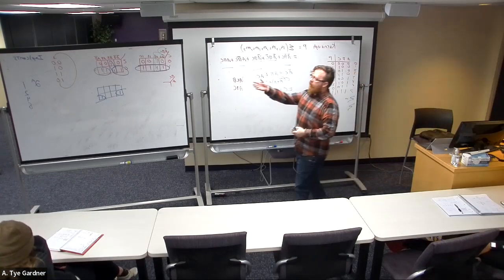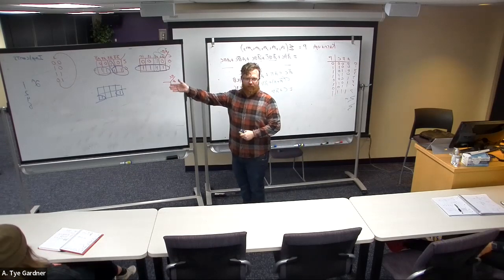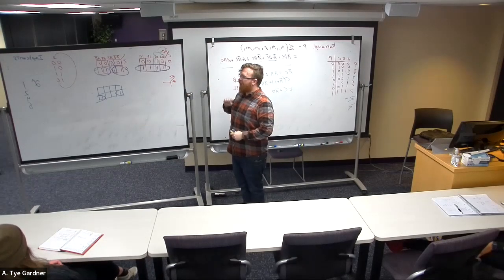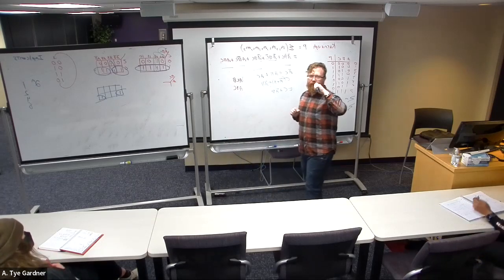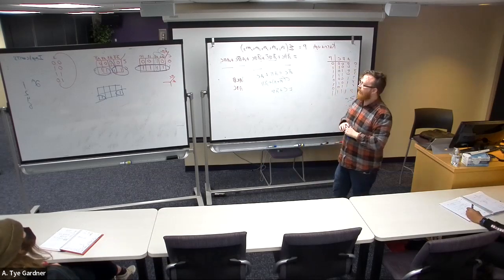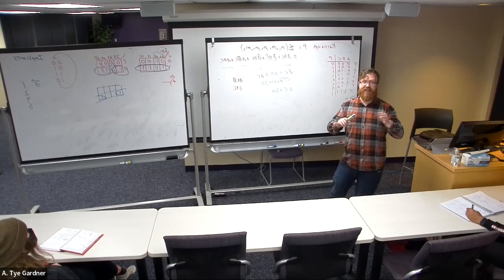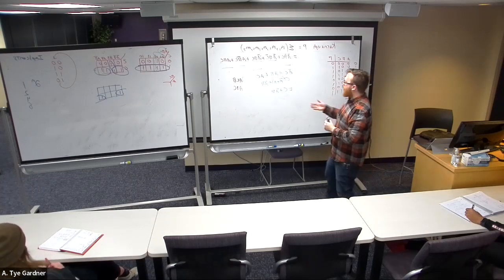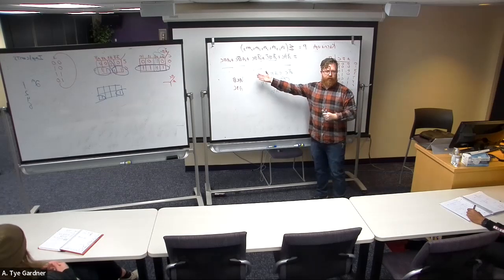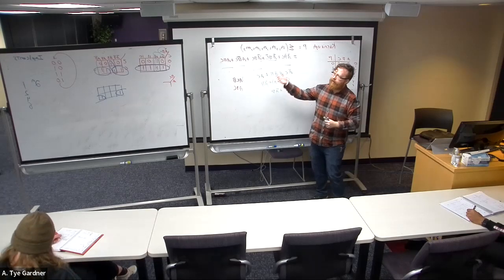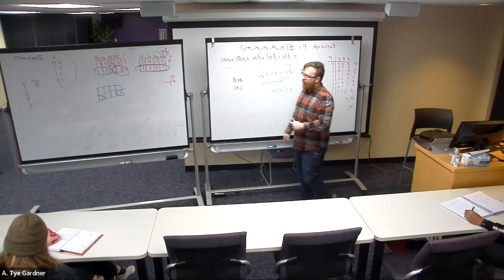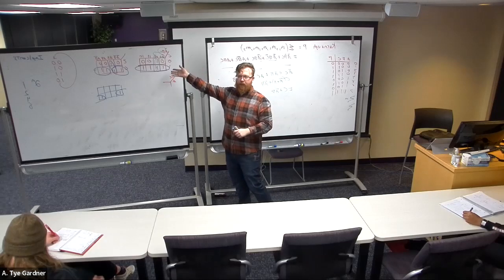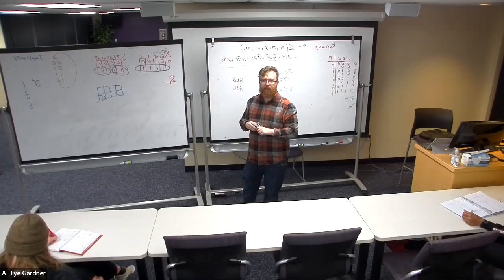Anyways, this is saying that as long as I have a square or a rectangle, I can circle that many ones. I am not allowed to circle 3 ones together. That is against the rules. If there are 3 zeros that are all adjacent, what if you just circle that? Not allowed, because I would need to add another of those extra terms, and there's not really a good way to do that on the K-map. There are other tools that simplify, but we're going to stick here. So it's sets of ones.